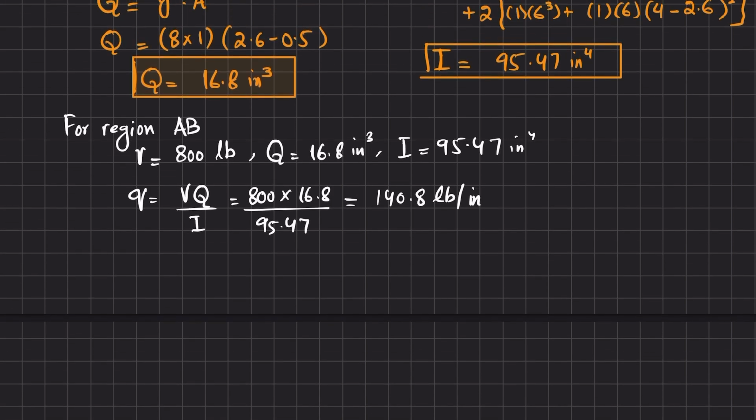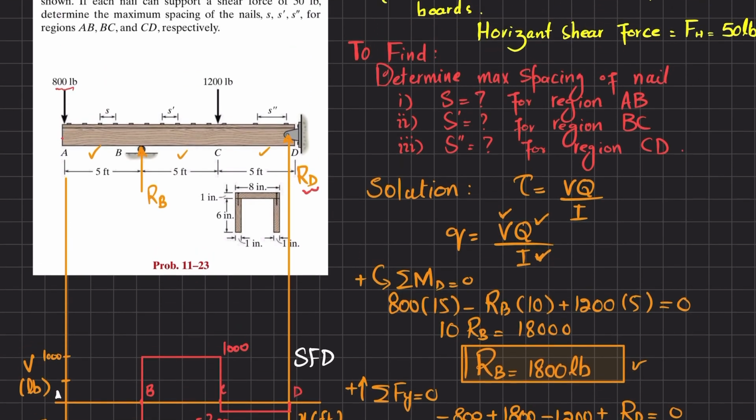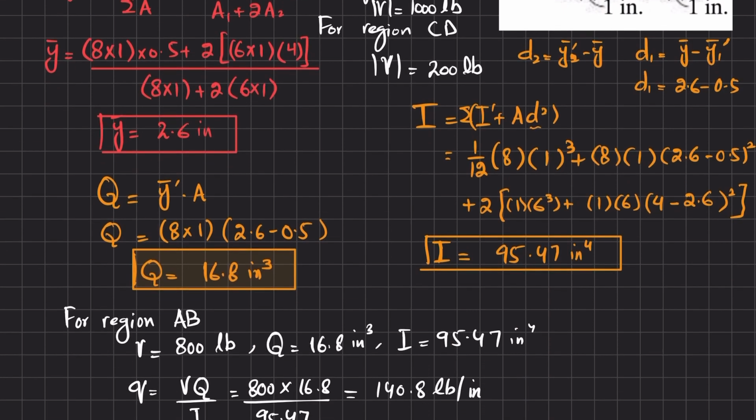So what we know is that shear flow is equal to horizontal shear force per unit length. Clear? So now here, if you look into the figure, this nail is also with this. So we will take this total distance, which is 2s, in order to find the shear flow over the length of 2s, and then we will convert it into s.